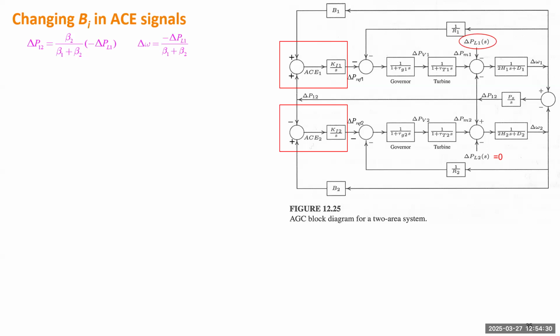So today, let's continue looking into the AGC control. First, we use this example with two generators connected through a single tie line to discuss how to choose the B values. Earlier, we developed those two formulas based on the governor control only, without any AGC. If there's no AGC, the outer loop of this block diagram will not be there. We only have just the inner loop.